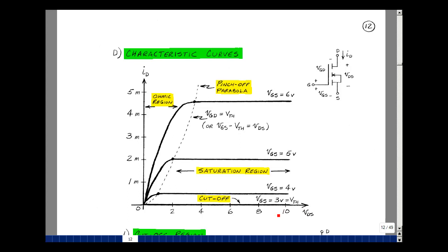3 volts. I've also drawn the symbol here for the N-channel MOSFET, and I've shorted the bulk to the source pin. And I did this because when you buy a discrete MOSFET, this is done internally in most cases. There's a few where they'll actually give you the fourth terminal out. But in doing IC design, we do have to hook up this fourth terminal correctly, and you'll learn about this